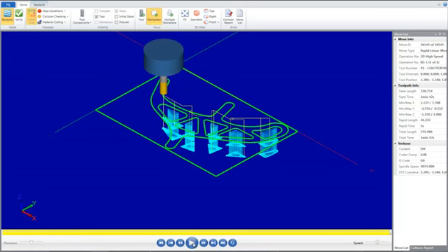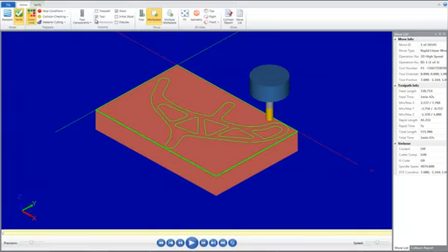Your toolpath will appear as shown. We will now simulate the operation and verify. From the Mastercam Backplot Home, select the Verify icon as shown. Ensure that Tool, Stock, and Workpiece are enabled. Now select the Play Simulation button to run Verify.